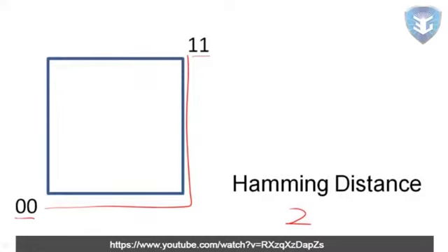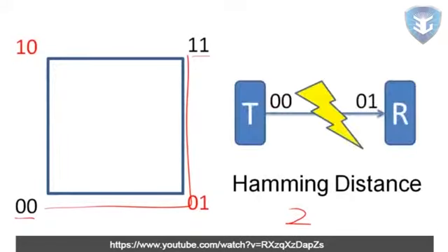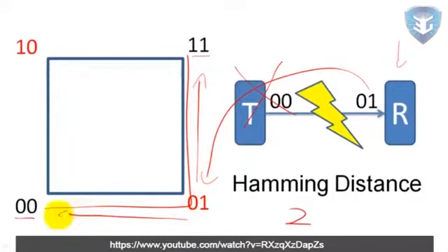In this situation, there are 2 potential bit encodings that would be invalid. If an error with 1 bit occurs, the receiving component would know that an error occurred because the received message does not match valid information. However, the receiving component could not correct the error because the error has an equal Hamming distance from both valid code words.